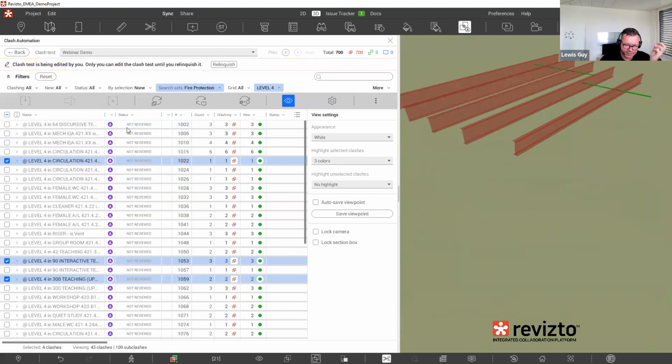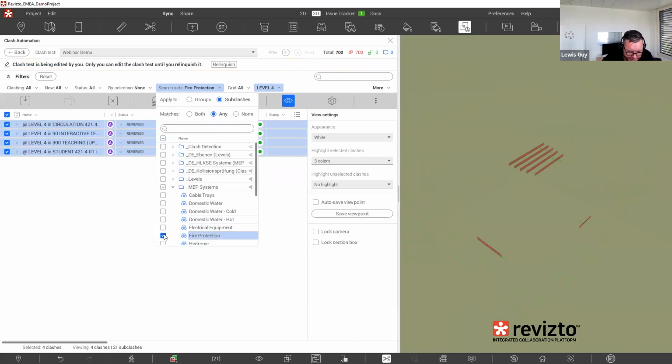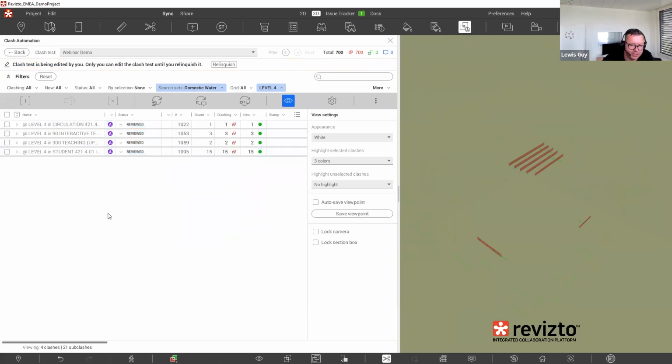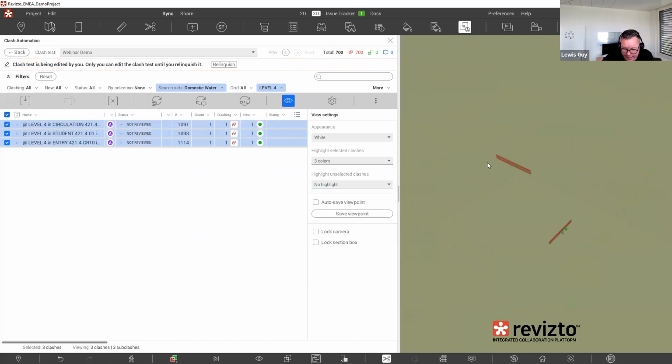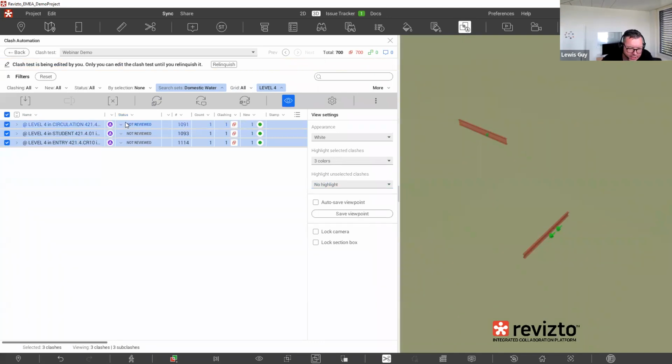And at this point we can say, okay, these are issues. So I'm going to mark those as reviewed. And in a moment, I'm going to create an issue out of them as well. But I'm now done with the fire protection and I can then come down here and say, okay, now let's show me the domestic water issues. So I can click on that. And again, I can see that there are 3 issues with domestic water at level 4. So again, I can review those ones.